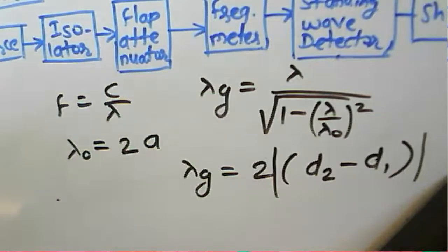In the RF substitution method, we measure the power using the device under test, then replace it with a variable attenuator and adjust the attenuation value to match how much power is attenuated by the device. So that's all about the measurement of attenuation and frequency, and all this measurement topic.